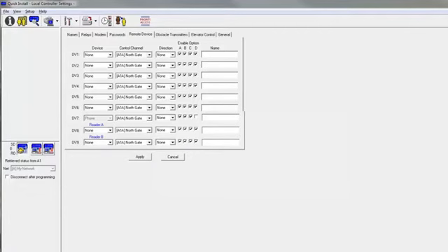Select Keypad for DV1. In this installation, we want that keypad to activate the North Gate, which is wired to Relay A. Select Relay A1A, or North Gate in the Control Channel window.